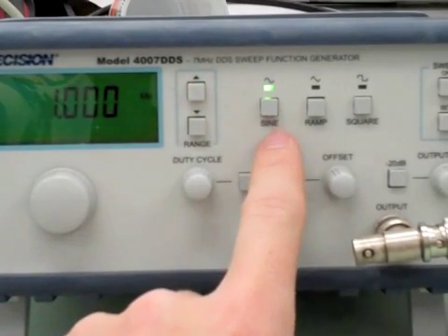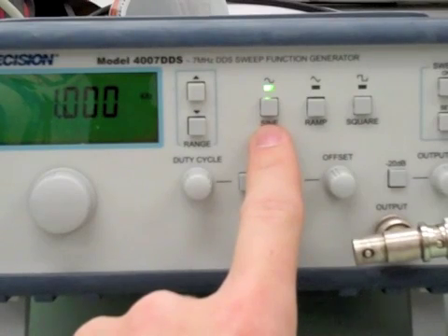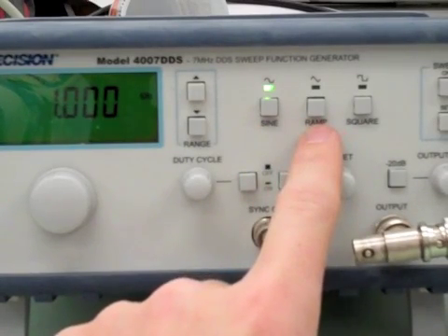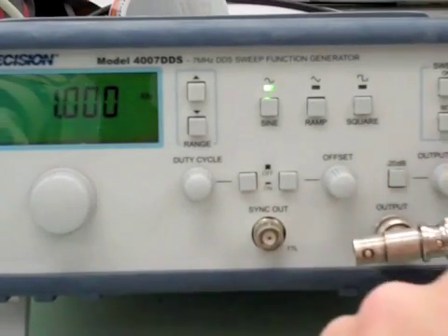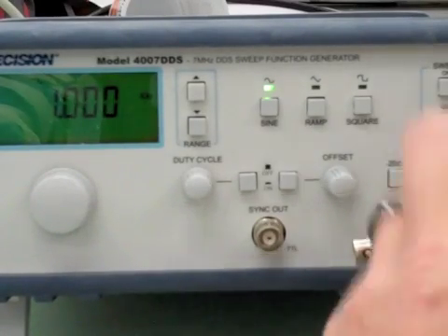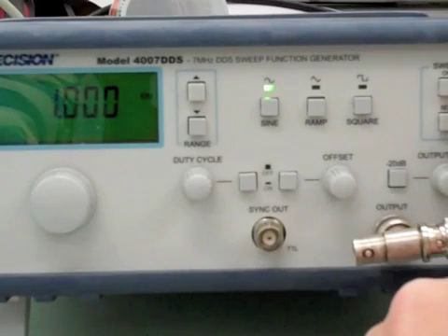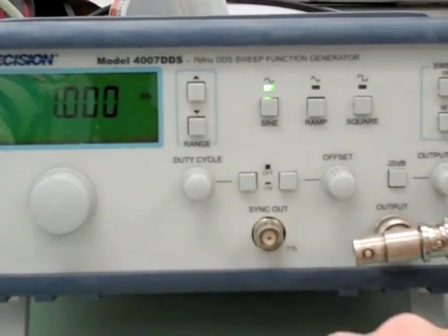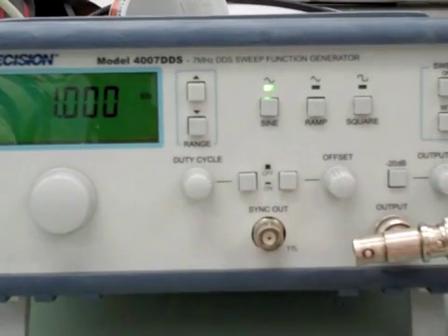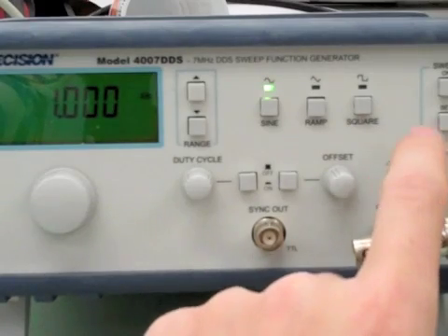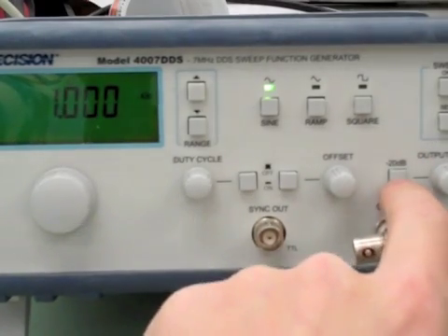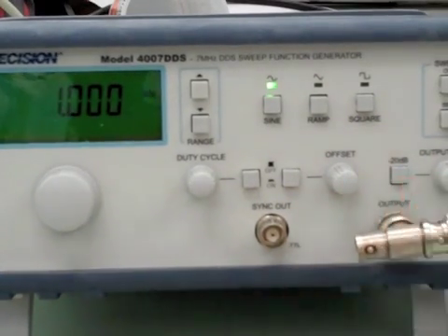We've got our output signals, so we've got sine wave selected right now, but we could also do a ramp signal or square wave. And over here we've got our sweep buttons. So this is just a function of the actual function generator itself. We won't be using this. We've got output level, so this will change the magnitude of our output signal. And you'll turn that on here. So it's turned on now. I can turn it off, turn it on.